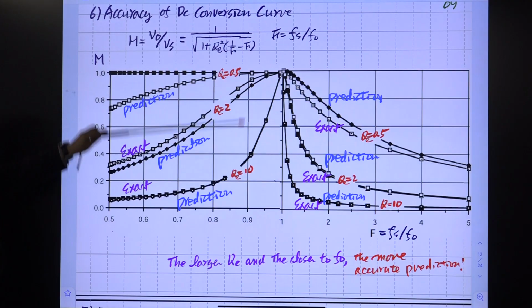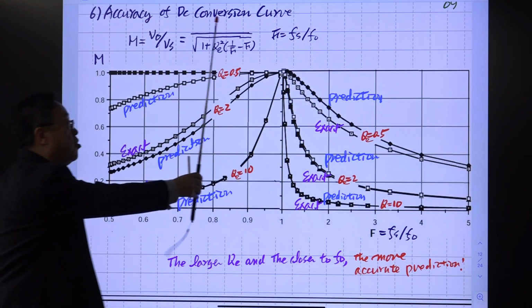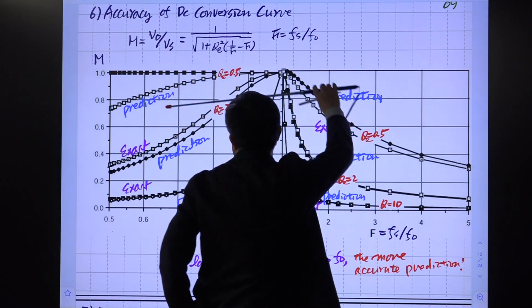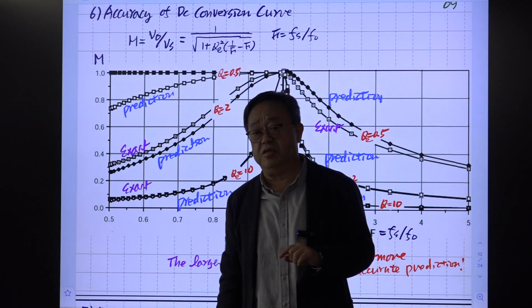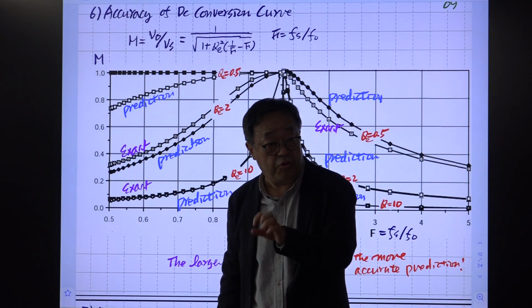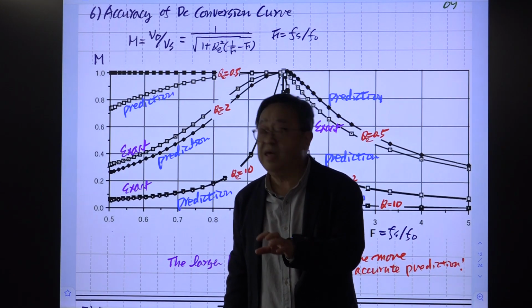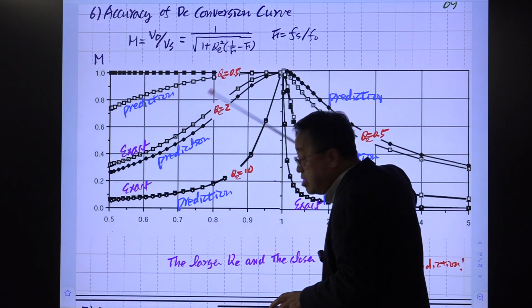This is the result of a different operational mode. In this region, below the resonant frequency with very low Q, the converter moves into an entirely different operational region. It shows some DCM behavior, discontinuous conduction mode, and the voltage gain looks strange, like this.